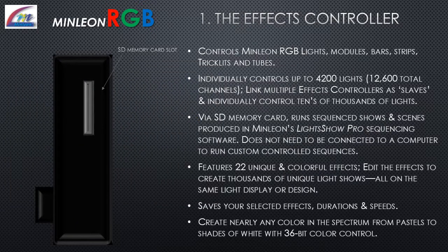Number 1. The effects controller controls Minleon RGB lights, modules, bars, strips, tricklets, and tubes. It individually controls up to 4,200 lights, 12,600 total channels. Link multiple effects controllers as slaves, and individually control tens of thousands of lights. Via SD memory card, it runs sequence shows and scenes produced in Minleon's Light Show Pro sequencing software. It does not need to be connected to a computer to run custom controlled sequences.